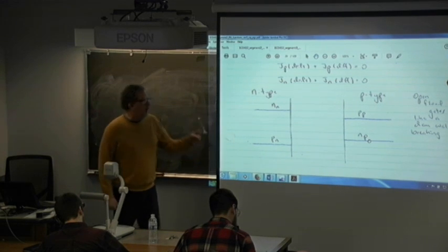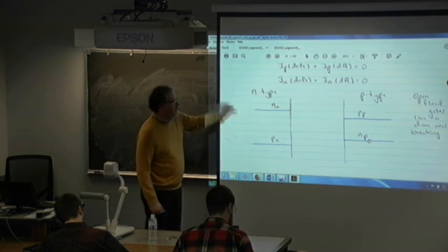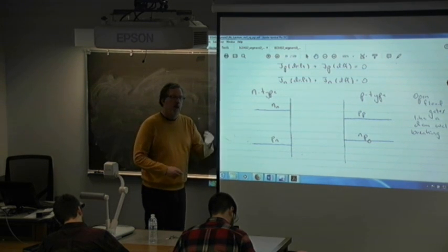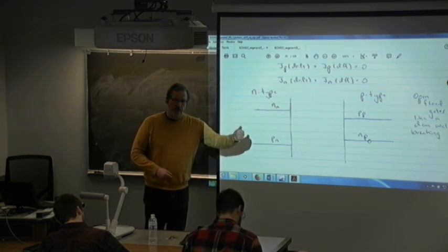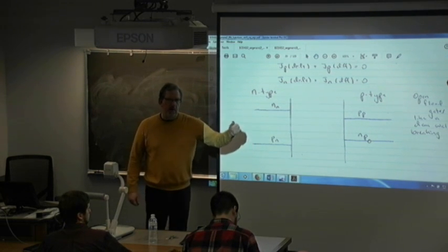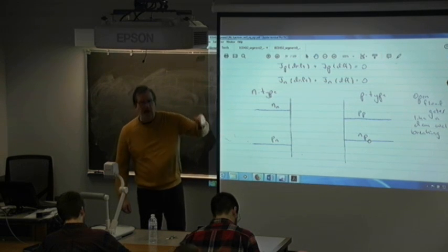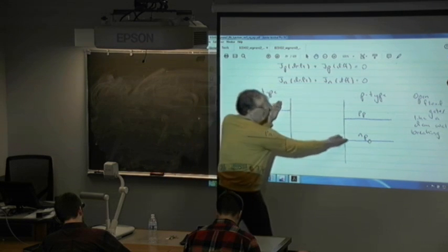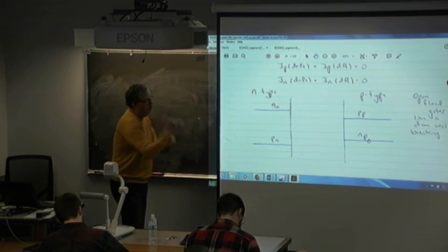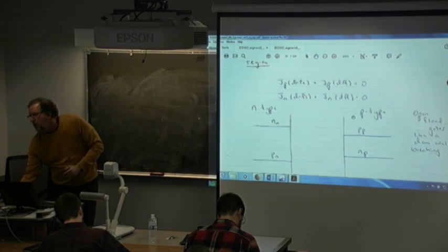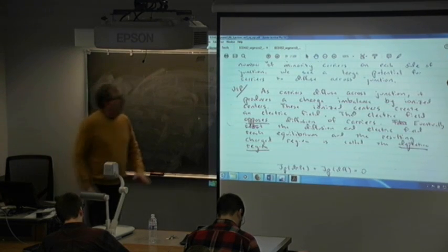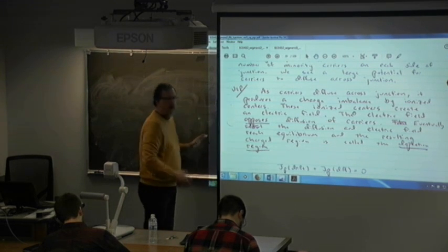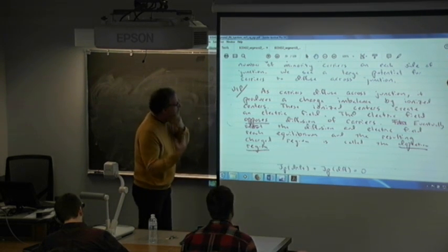And so far, at this point in the class, I had not taught you quantum mechanical tunneling yet. So the only way charge moves is drift or diffusion. And drift, remember this is first midterm material, drift is in the presence of an electric field, and diffusion is in the presence of a concentration gradient. So here we have a huge concentration gradient that will drive this across. So, this is a very staccato, very important kind of statement, but it might leave out a few details, but it's got the main gist.